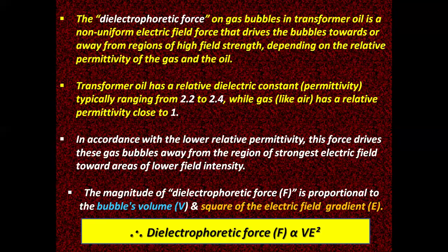The dielectrophoretic force on gas bubbles in transformer oil is a non-uniform electric field force that drives the bubbles towards or away from regions of high field strength, depending on the relative permittivity of the gas and the oil.